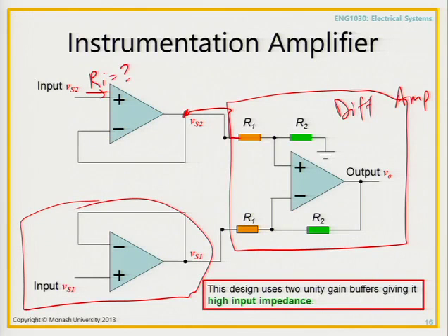of this op-amp? So remember, go back to the very first lecture when I said that you've got an ideal op-amp. What is the input impedance into here? So there was a resistor here connected like that. What is that when it's ideal? Infinity, yeah, I heard a mutter, infinity, yeah. So this has really high input impedance.